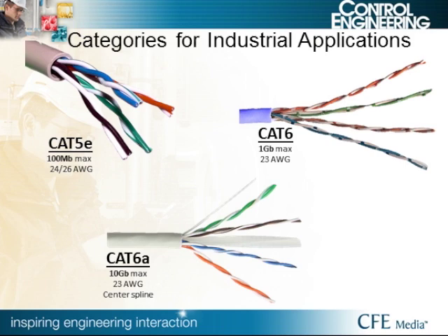Now, Cat 6a cable is required for 10 gigabit speed connections over 55 meters in length and up to 100 meters. Although 10 gigabit is rare in an industrial network, in fact, very few PLCs and VFDs have an Ethernet interface faster than 100 megabit per second. The 10 gigabit signal speeds cause excessive crosstalk that the twisting of the pairs within the cable itself cannot overcome.